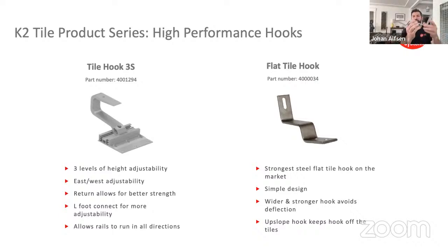This is our flat tile hook. You can see it's a little shorter. It's a little thicker. It has a kind of a raised section here, so it takes more flex onto it. So some folks who use tile hooks, or maybe are looking at tile hooks, don't like the deflection because you have your anchor here and your load here, and you have that deflection. But this one is built a little bit more stout, and works really well in those areas that might get snow, because we're starting to see Colorado come online with more tile roofs. A lot of times it's flat tile. So that flat tile hook is the stronger flat tile hook.